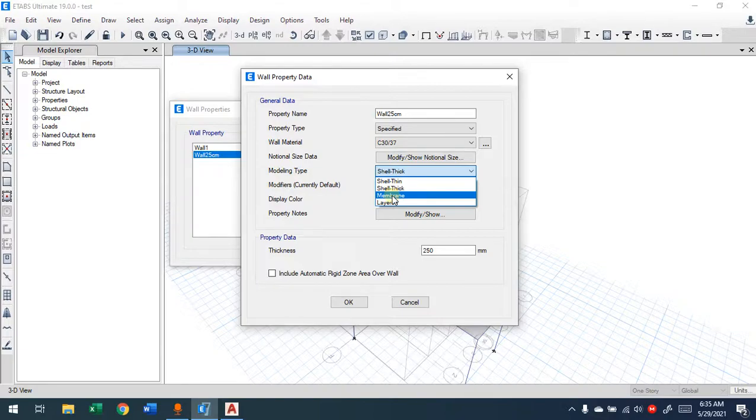Now, as a structural engineer, you are forcing the elements to follow what you're going to design for. Let's say that mainly shear wall will be used for the lateral load. You don't want the out of plane forces to make bending for the shear wall. So you are aiming the shear wall only to transfer the lateral load and the building weight, and you will design according to that one.